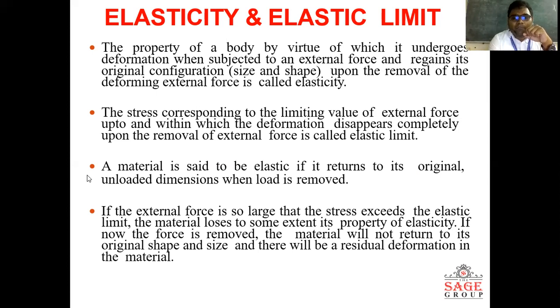When the load is removed, it should return to the dimensions it had before applying the load. Then that material is said to be an elastic material. If the external force is large, then the stress exceeds the elastic limit and the material loses, to some extent, its property of elasticity. If the force is then removed, the material will not return fully to its original shape, and there will be residual deformation set up inside the material.